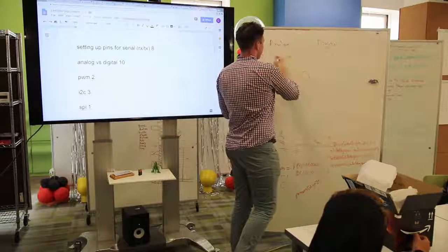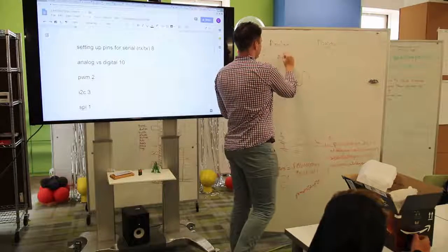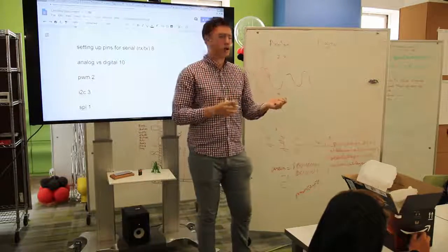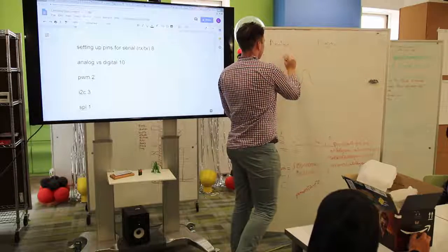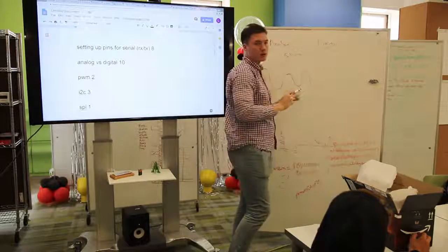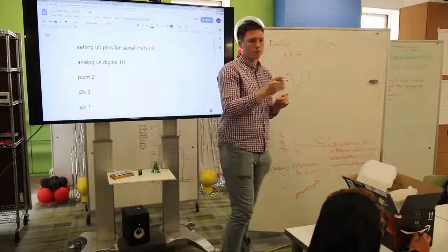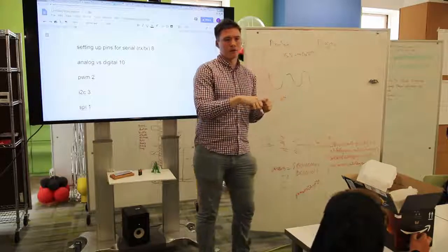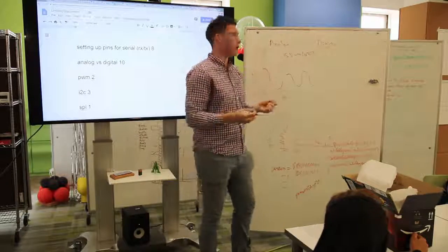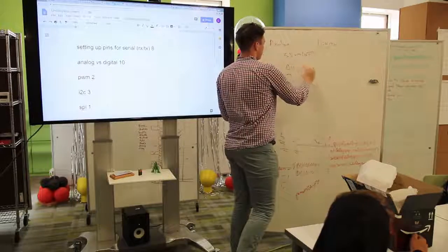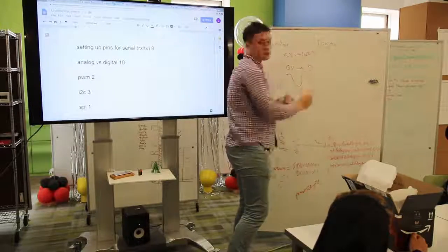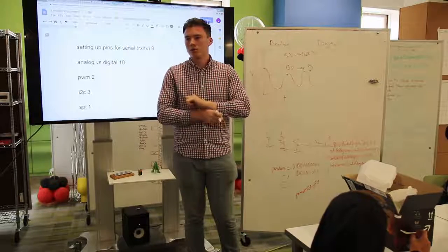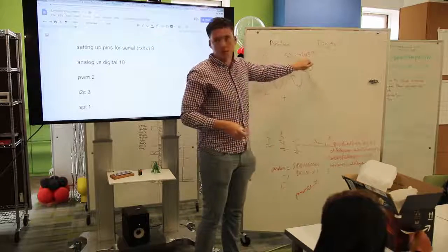So let's say that input was 2 volts. It needs to take on a value between 1,023 and 0. Well, the maximum, 5 volts, will correspond to what? Does anyone want to tell me? 1,023, exactly. So if you input 5 volts to the analog sensor, Arduino would tell you 1,023. If you input 0 volts, it would tell you 0. If you connect a separate battery, like 6 volts, it'll cap off at 1,023. It can't go any higher.